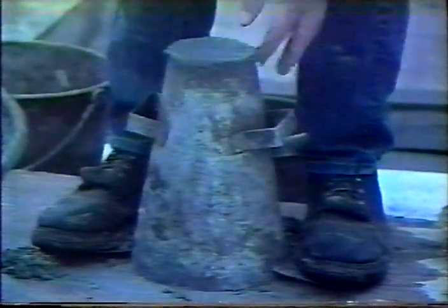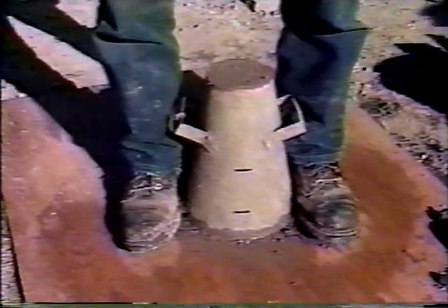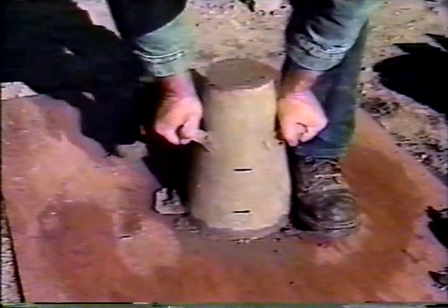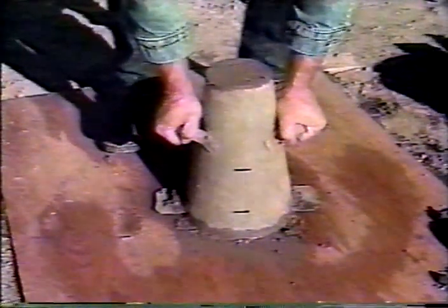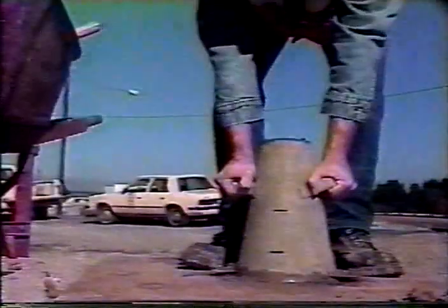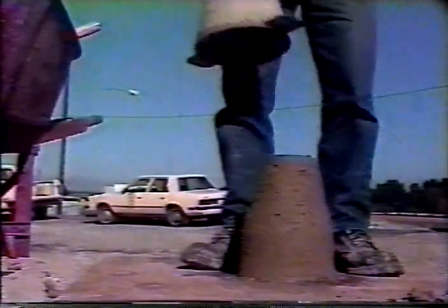Basically, both sides of the cone must be held still by pressure on either the handholds or footholds until the cone is removed. To remove the cone, both hands are placed on the handholds and downward pressure is applied to keep the cone stable before the feet are removed from the footholds. Now the cone is pulled straight up, slowly and steadily, without twisting or tilting. The removal should be completed in about 5 seconds. Slowly enough that the concrete doesn't pull on the cone.